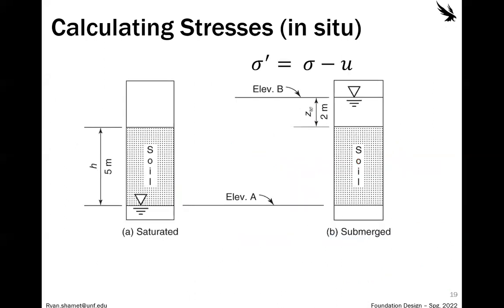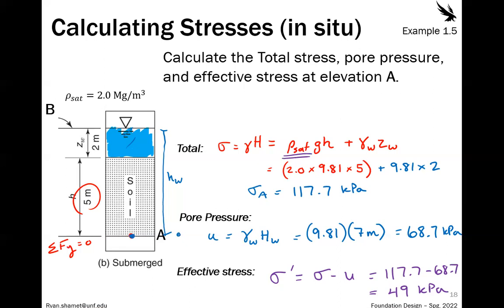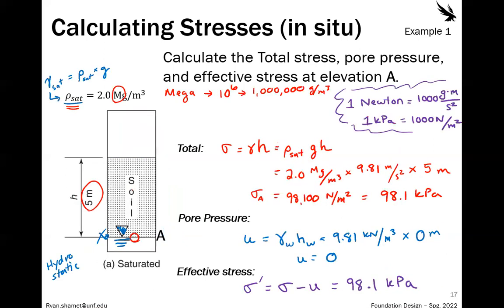That's a really good question though, because I remember the saturated unit weight then times 4. It didn't have the water. Actually, it did. So this soil can still be saturated. That's what it was saying here. It's just not submerged. If we were to zoom in here, you would see the soil grains and the water. And this is really common in clay. Sometimes the water table can be below the clay level, but because of capillary rise, if you remember that from geotech, the pore space can still be filled with water. So this is really common in a clay-like material. You might see that.